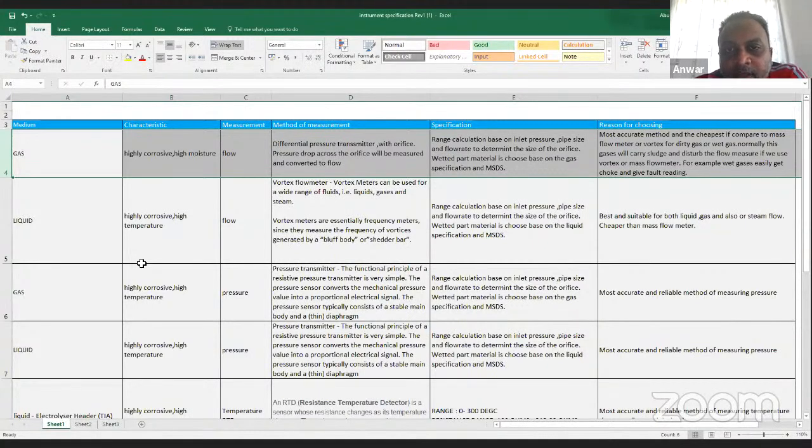Decontamination process will take place, and replacement of equipment could be done. But that involves a lot of study before we do that, because you will not have annual shutdown any day. So annual shutdown normally will take place maybe every 15 months. So what if any instrumentation require replacement out of those period?